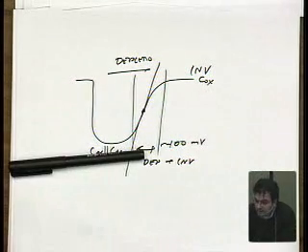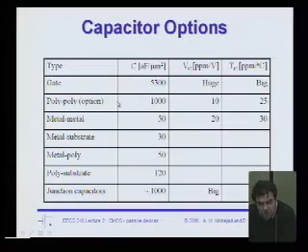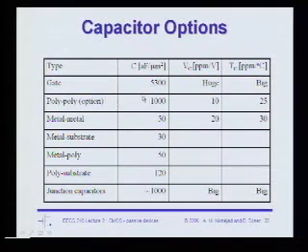Okay, back to the list. Okay, poly capacitors, they also don't have quite the same density, but they come close. But they are usually an option. They don't come standard. And again, we get the polysilicon depletion, which gives us a voltage coefficient.